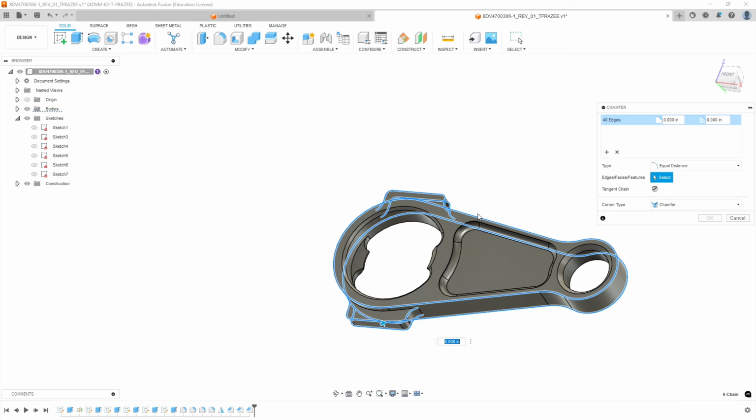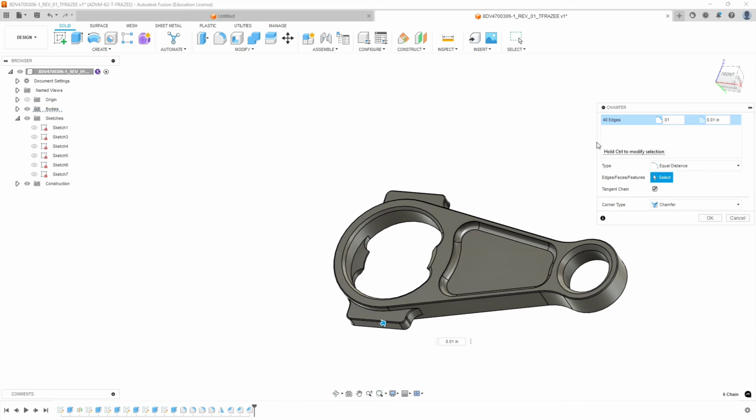And again, if we have problems with Fusion, it's actually easier to use a chamfer tool without them modeled. And that's why we're doing these last, so we can come back and suppress them in the model and cut them with parameters. But you have to be real careful in Fusion that you're punching in the right numbers. And if you receive this part from a client in third-party software, you're not going to have the opportunity to suppress those chamfers. That's okay.